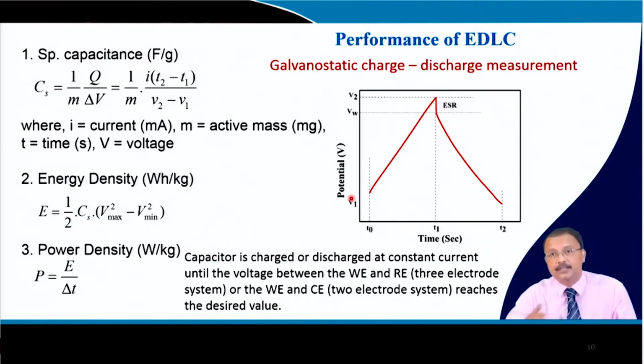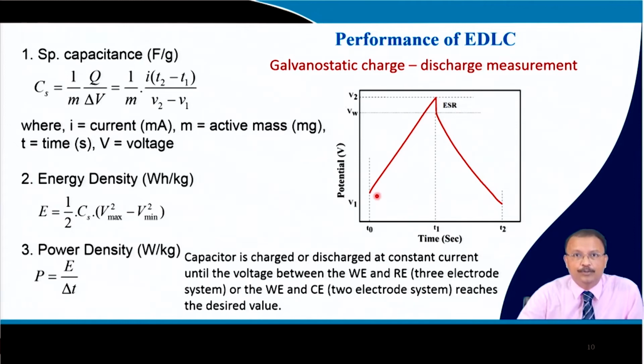You can also use the charge discharge measurement, and this will certainly be a straight line because it is the adherence of the charge and coming out of the charge from the surface. So, it is a straight line, and this drop usually comes from the series resistance of the capacitor that I have already defined. So, you start from your open circuit potential and then go up to the maximum of the voltage window, and then there is a drop due to the value of internal resistance,